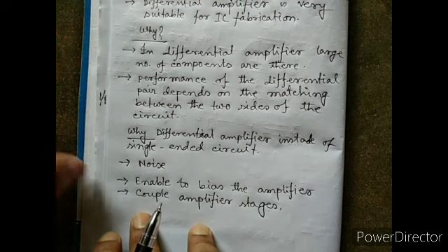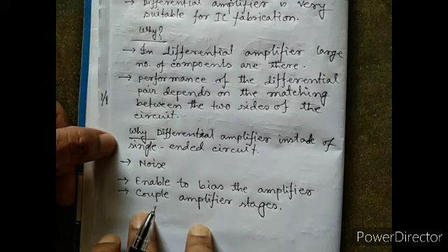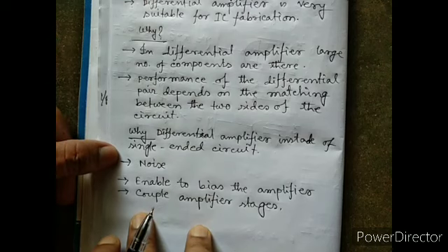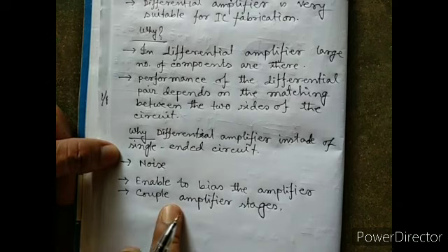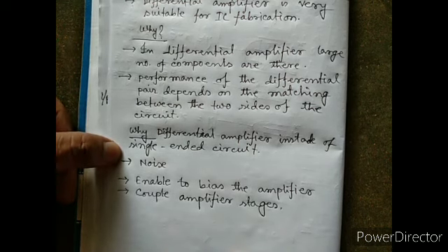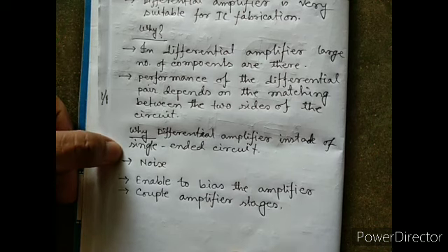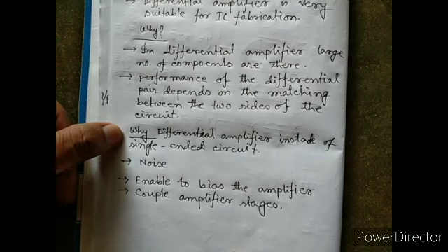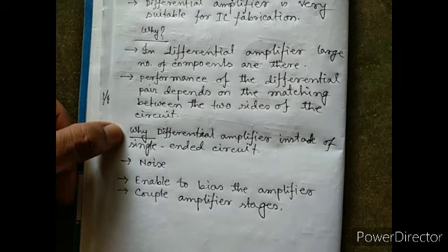As the differential amplifier takes the difference of the two inputs, the same noise inputs will be cancelled, so no noise effect will be there. So the differential amplifier is well suited instead of a single-ended amplifier.